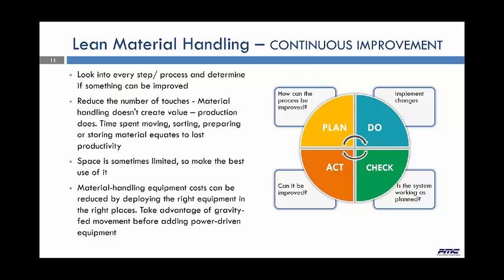Now, especially try to keep the distance short between your warehouse and your assembly line. And at certain places, try to use some gravity to help you out. So you can have a gravity flow conveyor, you can have racks. You can drop it off, and because of it, you can have sloped racks where it delivers to the line. So you need not walk all the way 10 feet or 15 feet to the station.